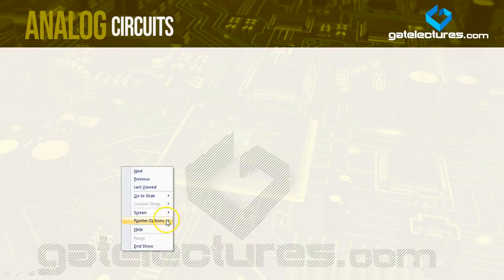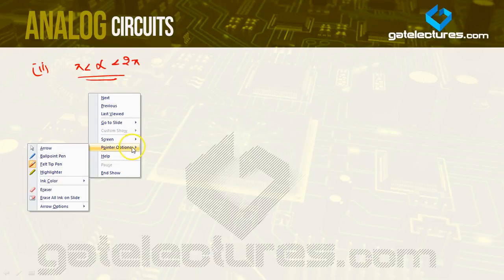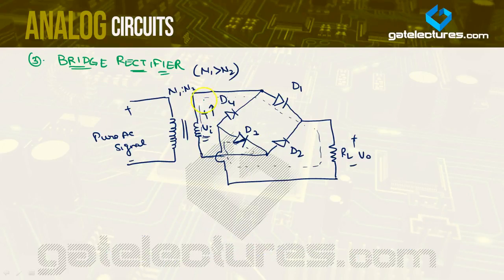Now the other case, case 2, when alpha lies between pi and 2 pi. In this case Vi is negative, and D2 and D4 are forward biased. D1 and D3 are reverse biased. They are open circuited and the others are short circuited. So the current flows in the loop through D4 and D2.